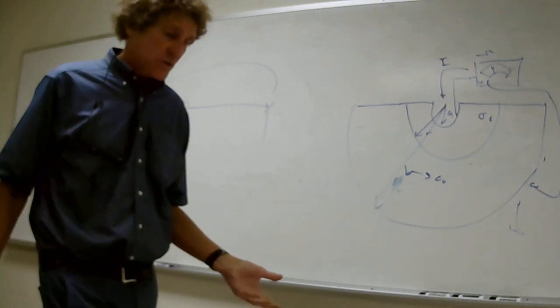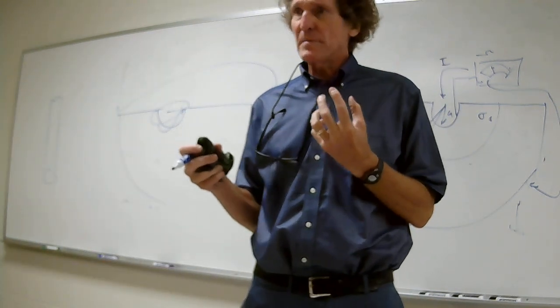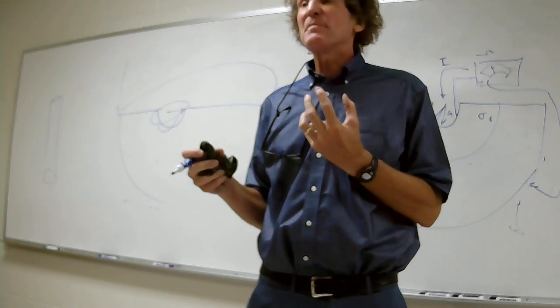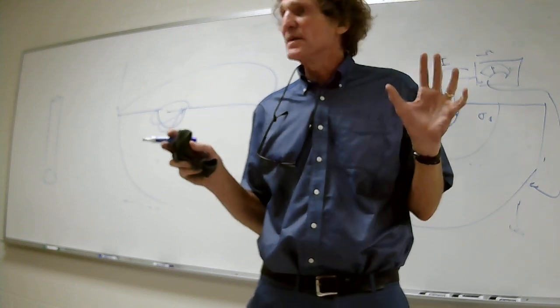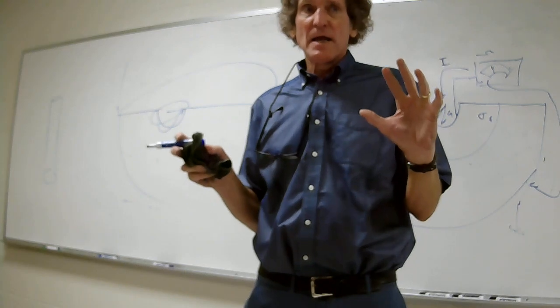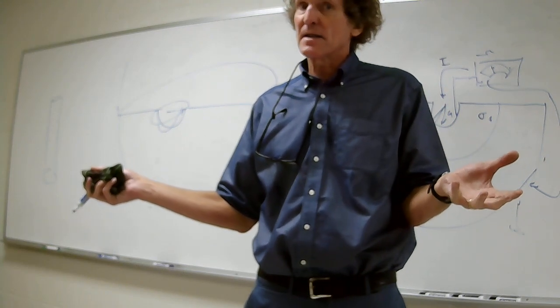I think I mentioned this here. Do you remember what the conductivity of air is? I told you this. Is this the 10 to the minus 5 number? It's 10 to the minus 14, okay, 10 to the minus 15th, roughly. Sometimes it's about 10 to the minus 5 times 10 to the minus 14, all right? And it's 1 over ohm-meters. Very, very low conductivity.